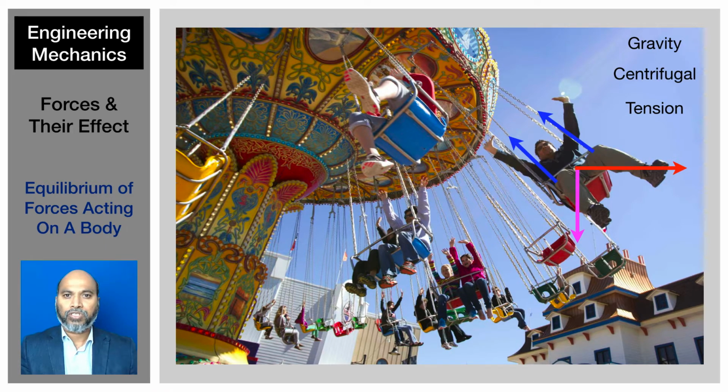The only motion here in this case is in the theta direction. So if you limit your problem to the radial direction, r and z, which is the vertical direction, and analyze the problem, you can apply statics to determine whether or not this person sitting here on this merry-go-round is in equilibrium. Okay, so you've got a new force added here, centrifugal force, again, which is also a force without contact.